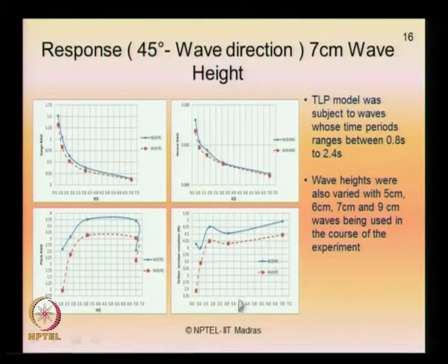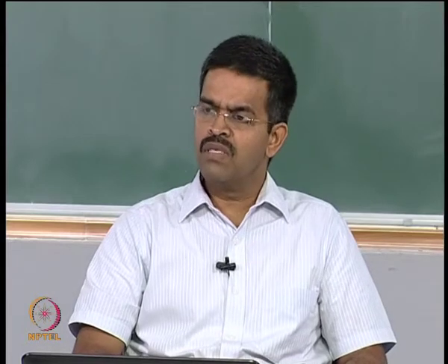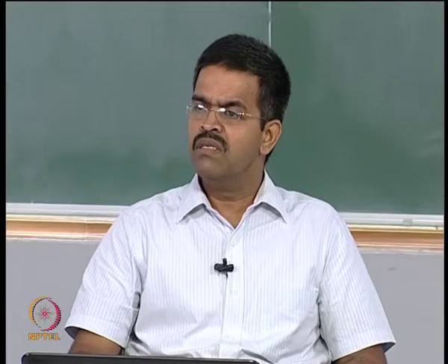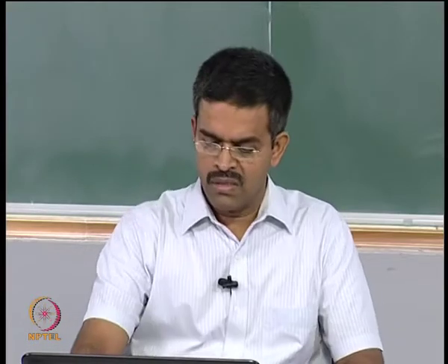As you see, the increase in H by L causes significant reduction in the tether tension variation as well. So, this can be seen as one of the ideas of retrofitting the members, which can also reduce the tether tension variation in the cables or in the tethers.